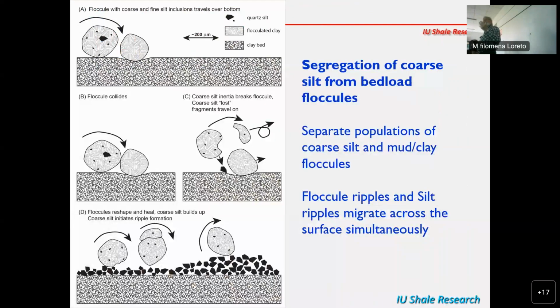The way it works is basically like this. If you have a floccule that forms spontaneously in turbulent flow, it may contain larger silt grains, 20, 30, 40 microns or something like this, maybe 60 microns. And then they're surrounded by a very loose matrix of clay minerals and fine particles. And that thing is moving sort of in a fluid. Everything has the same acceleration and everything.